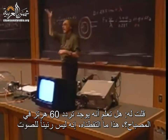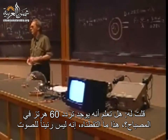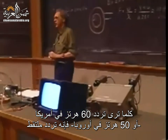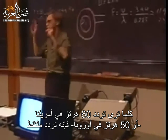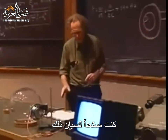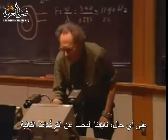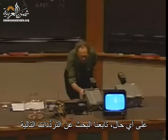And I said to him, you know the 60 hertz are the lights in the building. That's what you pick up. It's some crazy pickup. It's not a sound resonance. Whenever you see 60 hertz in the United States, it's pickup. If you see 50 hertz in Europe, you know it is some pickup. So I was willing to forget about it. In any case, we went on and we were trying to find the other